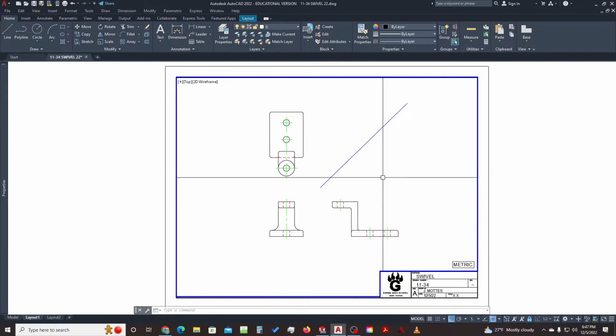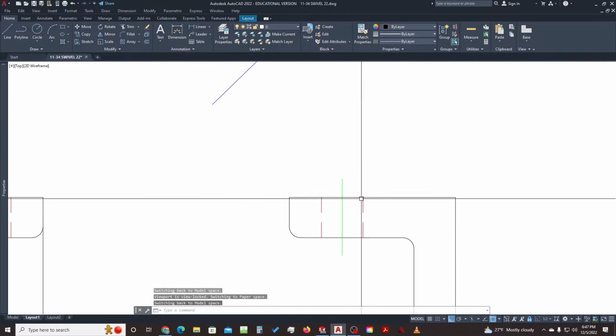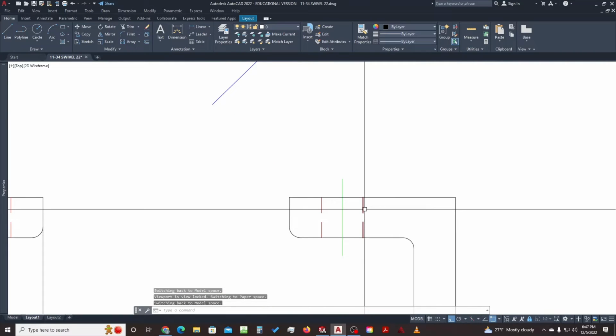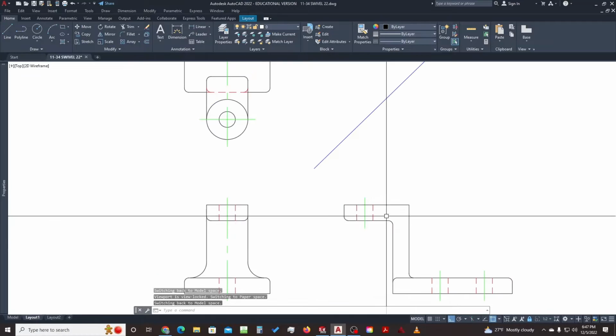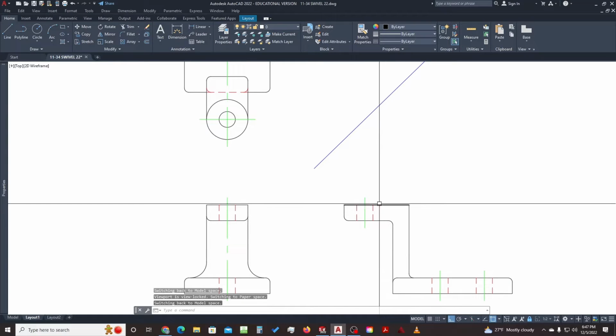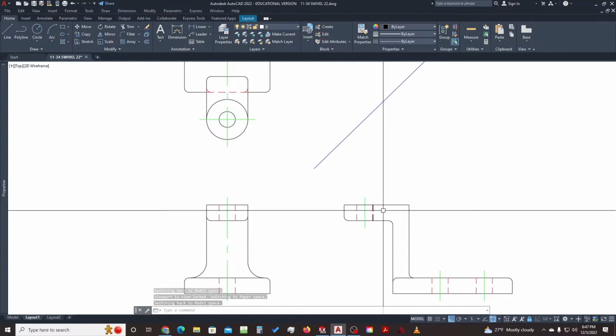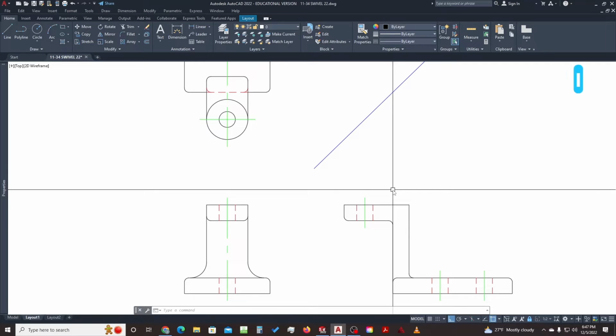Okay, so my line type scale, well, it's showing up. Center lines are not. Hidden lines only have 2 dashes on my smallest distance. So we want center lines to have a minimum of 3 dashes. So I'm going to try another line type scale. It's going to have to be a little bit less than 10. I'm trying 8. 8 doesn't work. I'm going to hit enter twice and try 7. Nope, still no good. Let's try 5.